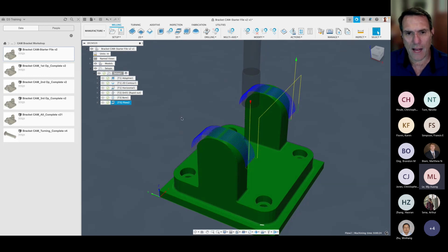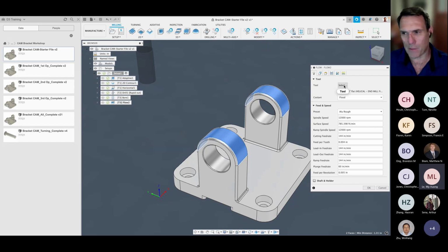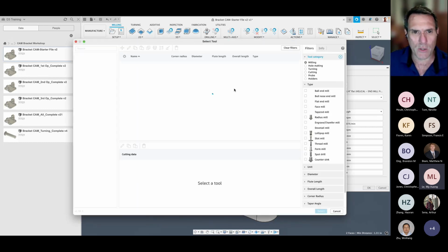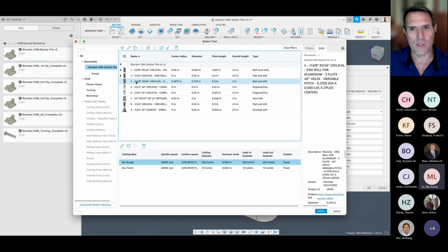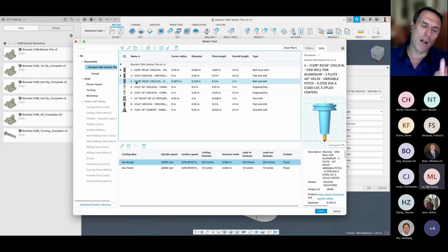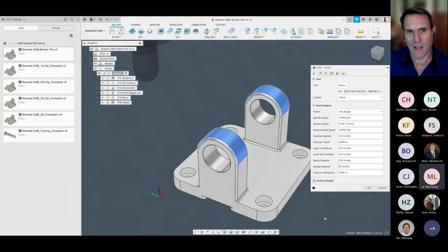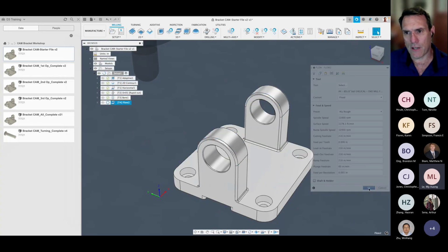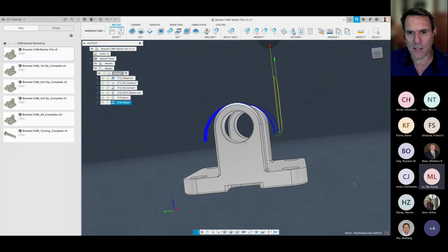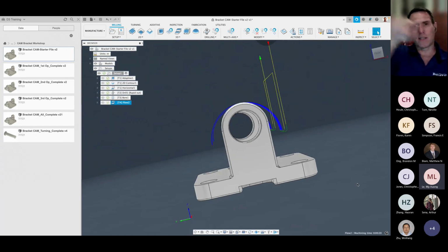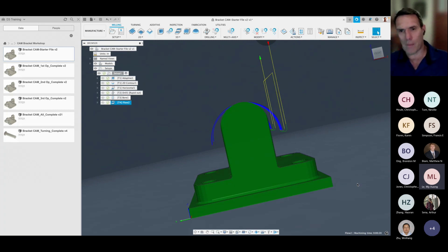Okay, so see how that looks, and then compare it to when I put the correct tool in, pardon me. I need to change my tool. I'm going to change it to number 4, which is a ball end mill. A ball end mill has a semi-spherical tip, a completely rounded tip. And once it generates the tool path using that, you'll see instead of it going down and having a sharp corner drop off, it's a smoother arc around either side.